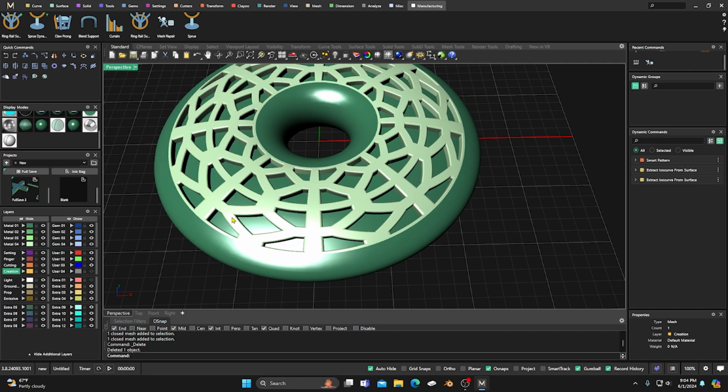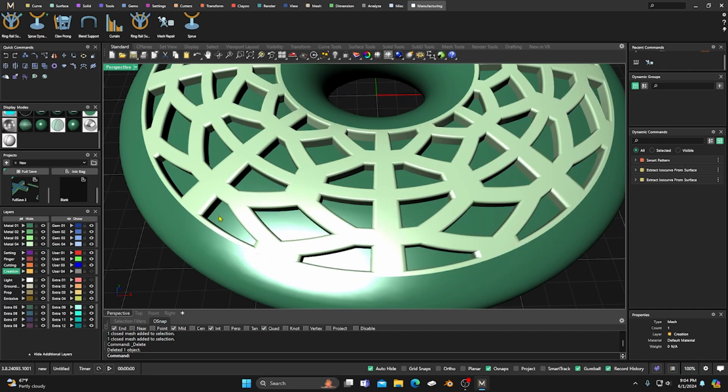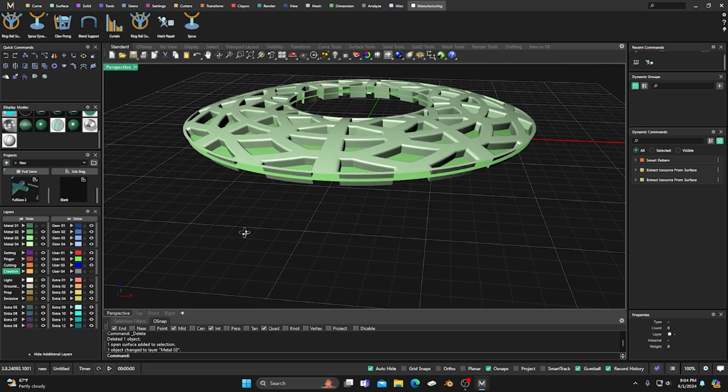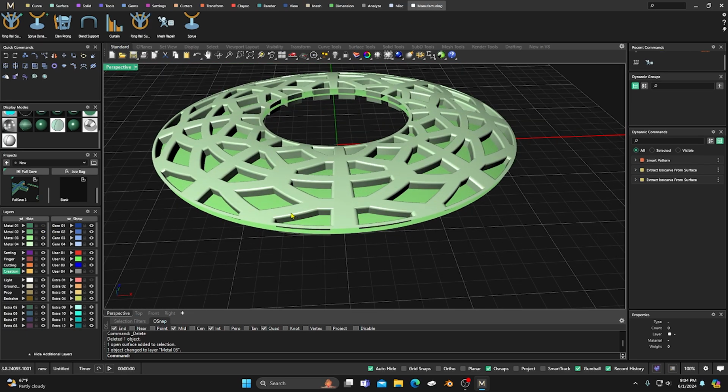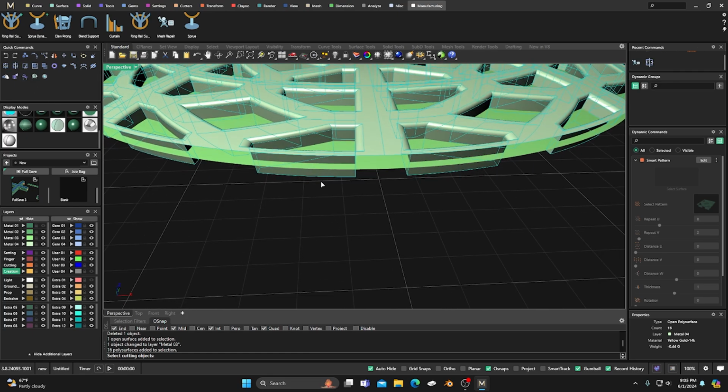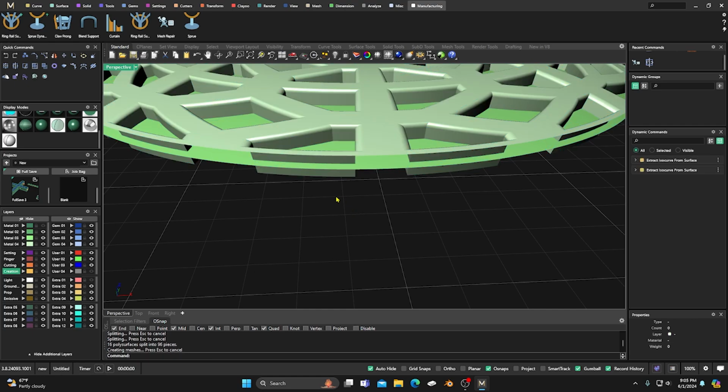So right now I have this out here. I'm going to take this surface here, and we'll change it to this, and then I'll turn off this because we only need to work with these two surfaces, right? And first thing I'm going to do is take all my smart flow pattern there, and I am going to go ahead and split it with this surface down here, right? And then hit enter. Okay, and just wait for that to go through and do its deal.